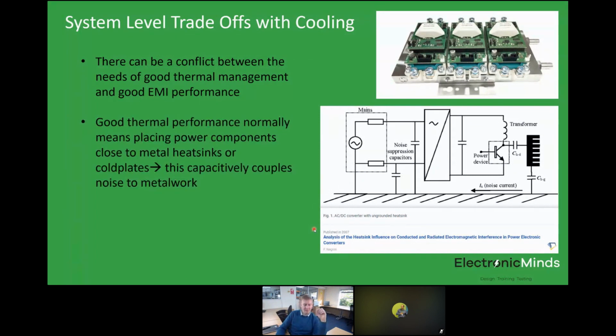And the reason for that is that to get good thermal performance, you need to couple very closely with low thermal impedance the source of your heat to a heat sink. And to do that really what that means is you want to have them very close to one another. Now that's great for meeting the requirements of thermal performance. However, that's a disaster potentially for EMI.